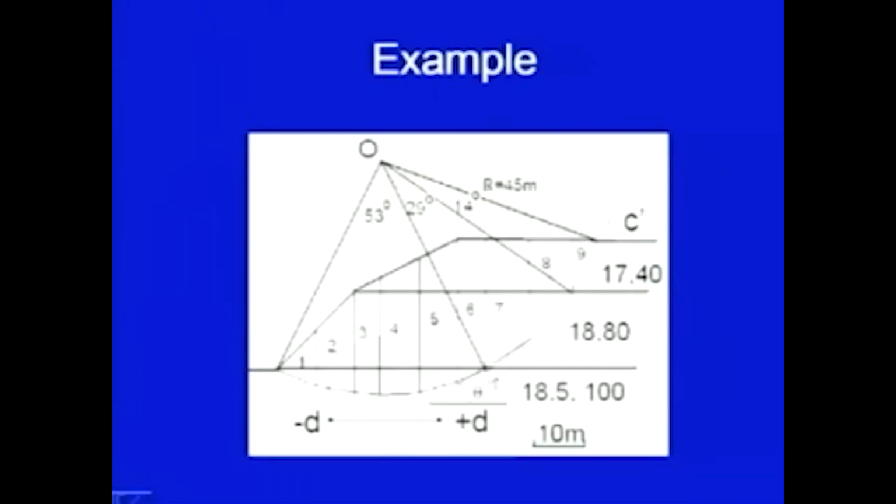I have taken one slice ending here and here at the intersection of the failure surface and where the profile is changing, so that the calculations will be simple. This entire material in one slice will be having one property, this will be having one property. Theoretically, you can take as per your convenience any number of slices.